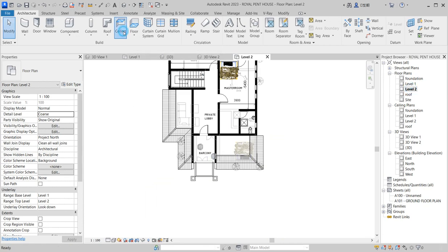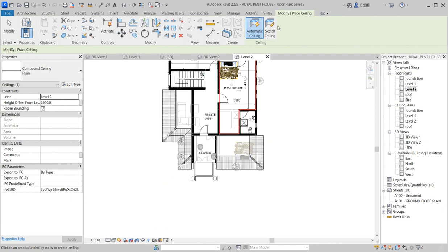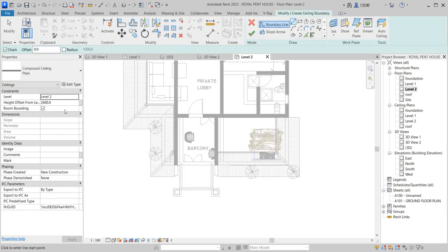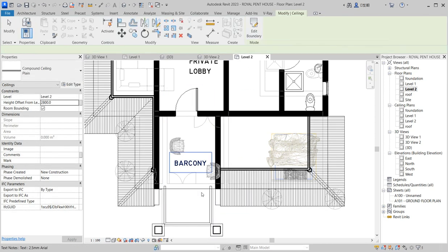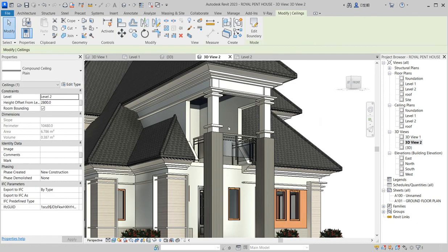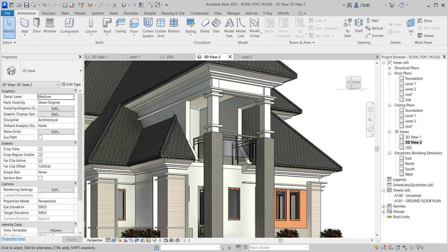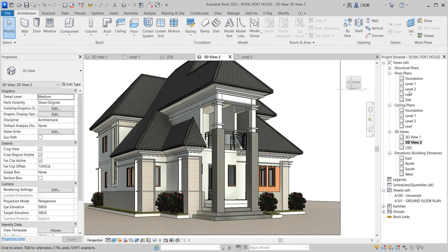So you go to click on ceiling. From ceiling, you start sketch. So you sketch accordingly. You use this one up to 2800. So then you do rectangular drawing and fix that into a position. So you click finish and see how far. So go to your 3D camera and see what you have created. Is it? Yes, that is what it is. So you close.